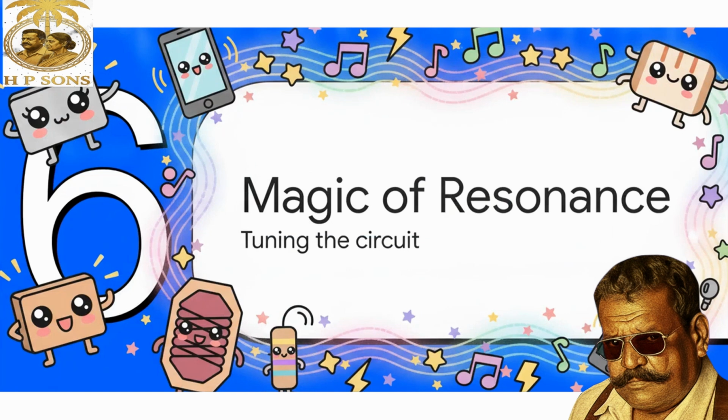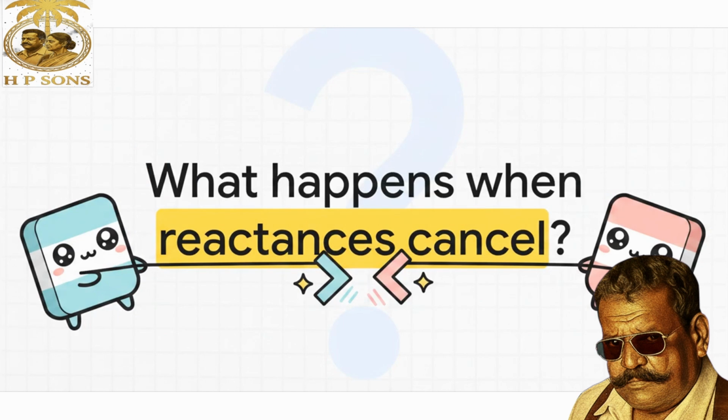And that brings us to section 6, the magic of resonance. This is the grand finale, where these three building blocks create something truly magical for our everyday technology. Since the inductor lags by 90 degrees and the capacitor leads by 90 degrees, their reactances are in a constant, invisible tug of war. But what happens if we tune the frequency of the AC source so that those two reactances are perfectly mathematically equal? What happens when they completely cancel each other out?